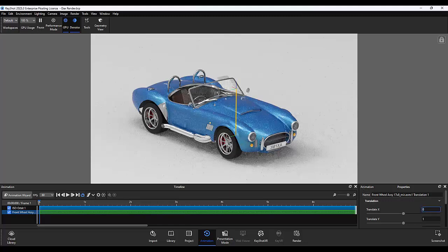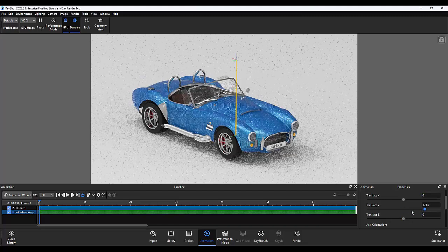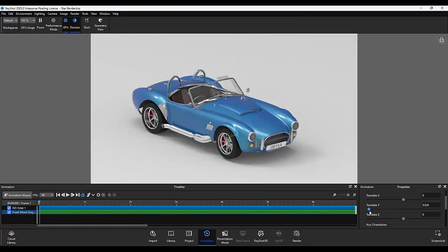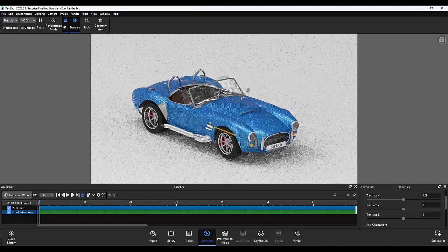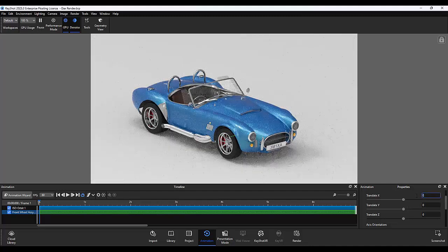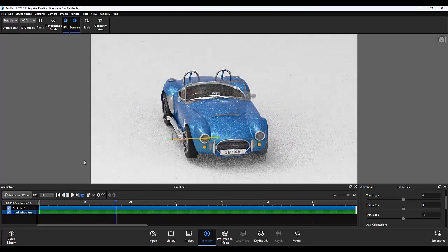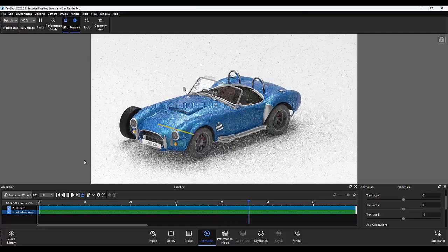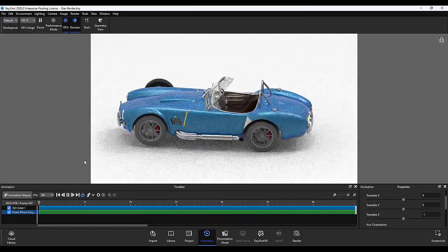So looking at these properties, I'm going to go ahead and just redefine my parameters. Again, if I specify the Y to 0, then this is going to start me off from a completely neutral position. And from here, if I wasn't too sure of what I was going to adjust, I can now use the sliders to see exactly where the model is going to go, or the direction of where the model is going to go, before I start to commit to any form of settings. So I've now gone ahead and specified my Z translation to -1, and that's looking about correct for me.